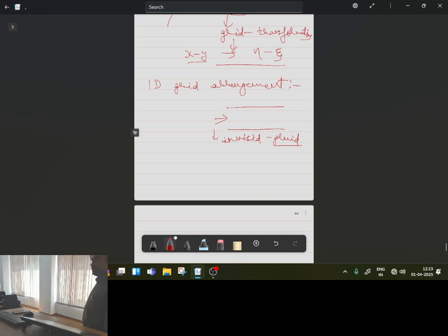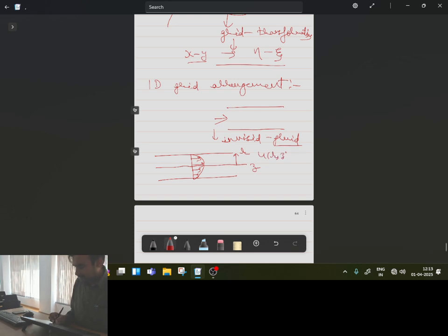So this is my pipe, and if I consider that a viscous fluid flows, what happens? I am having generation of velocity profile something like this. Okay, where if this is the axial location z and this is radial location r, in both the directions r and z velocity is actually varying. So velocity is a function of both r and z.